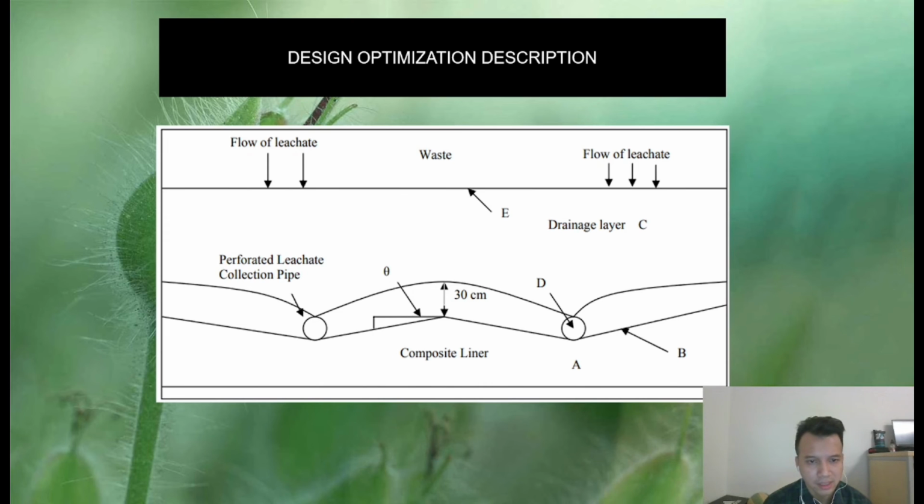The filter layer is another technique that is employed to prevent the actual blockage of the system. This layer of geotextile and sand is positioned directly above the draining blanket. Its purpose is to prevent waste from entering the draining layer and the collection pipes, which would otherwise result in the formation of physical blockage in the flow. Clogging of the leachate collection system